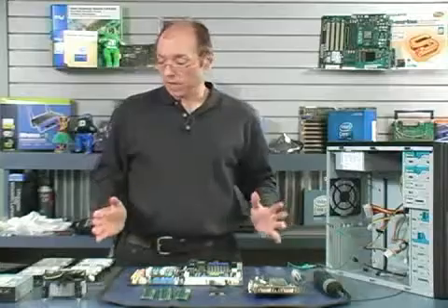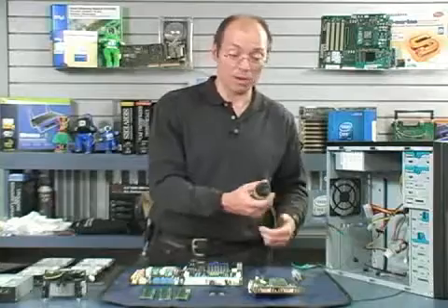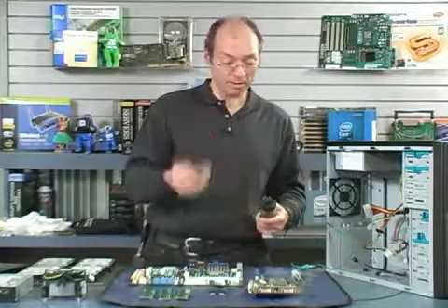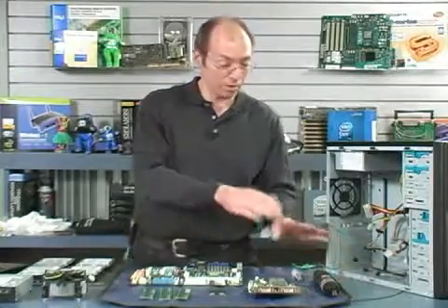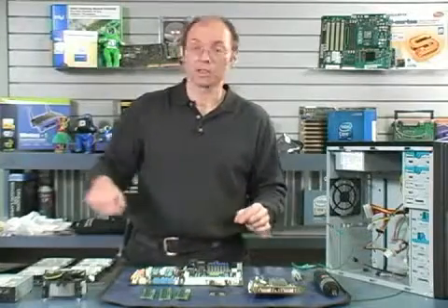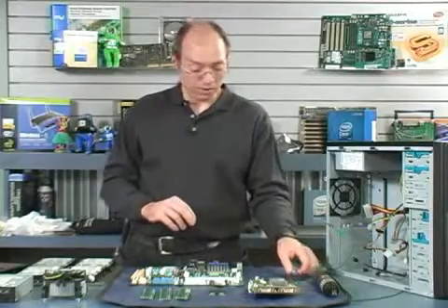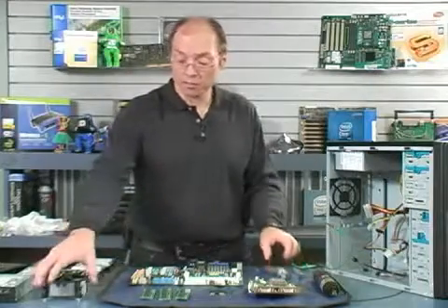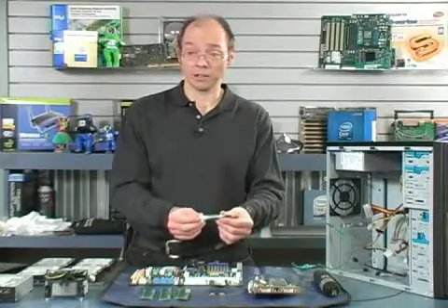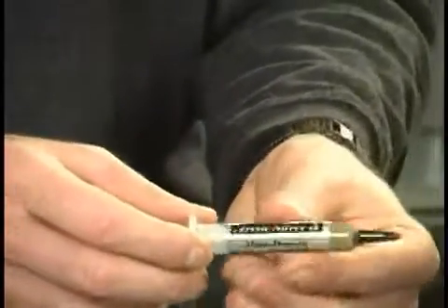So I've got all my parts laid out, everything's ready. A couple of tools that I'm going to need. I basically do almost all of my work with an electric screwdriver. Some people prefer to use a manual screwdriver. That's fine. It just may take a little bit longer. With an electric, you do have to be careful. In some cases, you don't want the bit jumping out of the screw head and trekking across the motherboard, causing damage and things like that. So that's one thing. Also, if your heatsink doesn't have pre-applied thermal interface material, you're going to need something like this, which is some thermal grease, to put on top of the processor to better transmit heat to the heatsink.